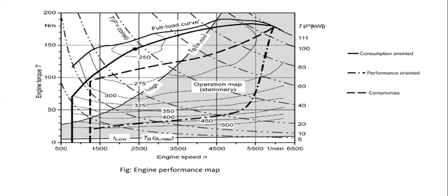Before the exhaust emission regulations were introduced, the air fuel mixture used was based on the ratios required for either maximum power or maximum economy. Unfortunately, the 12 to 15% enrichment from the chemically correct ratio to provide maximum power also produces a high emission of CO, HC, and NOx in the exhaust gas.